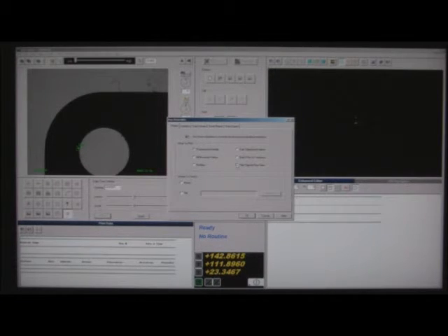This lets you monitor people's progress where intervention is required in the program. You may be requiring the operator to put in a lot number or something for statistics so that you can identify a serial number on the part. You may want to go back and have them measure something on the part and have it included with this routine.